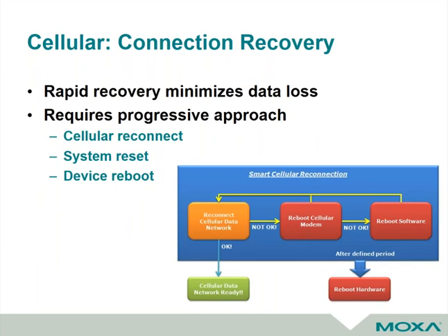Likewise, most of the companies providing communications products and even industrial control products don't always build all of the parts that go into these. A lot of these are using commercial off-the-shelf modules. So it's really important that those suppliers have a real robust mechanism for recovering those connections. A lot of things can go wrong with cellular. Talk to your supplier or your potential supplier and make sure they've got a really good strategy for handling this. In the event of having dual SIMs, that's important. But what happens if you lose the cellular connections? What's that recovery mechanism look like?